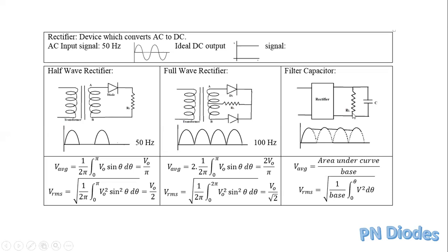When you put a capacitor across the load resistance, what will happen is, when the current is coming in, the capacitor gets charged. And when the current is dropping down like this, the capacitor will supply. That's what the line here shows: that the capacitor is supplying the energy. So understand it carefully. You know that a capacitor stores energy and then gives it back.